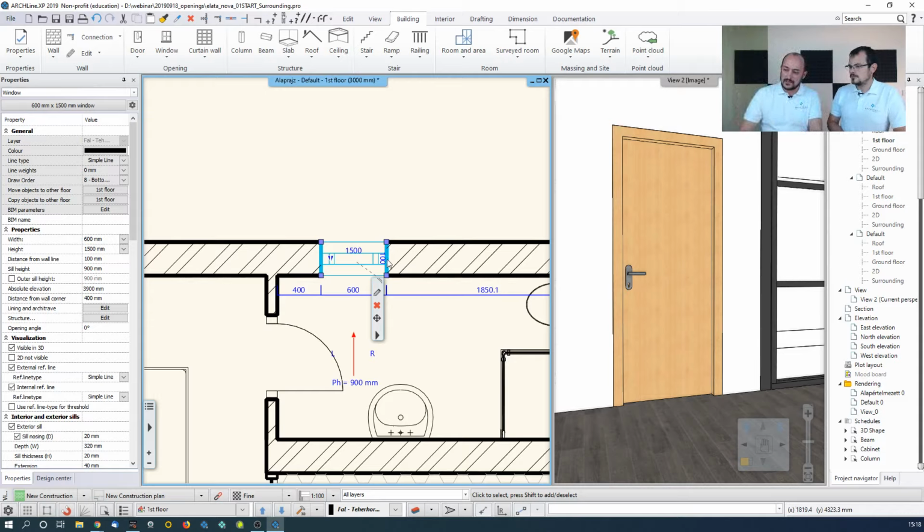So let me change it so we can see how it looks. This should be, for example, 50, half the original. Now it comes closer to the inside. Yeah, so it's coming closer. This is actually the distance between the placement plane and the window. So to change it back, I just write it again to 100, and then it changes the position. So this is how you can do that.